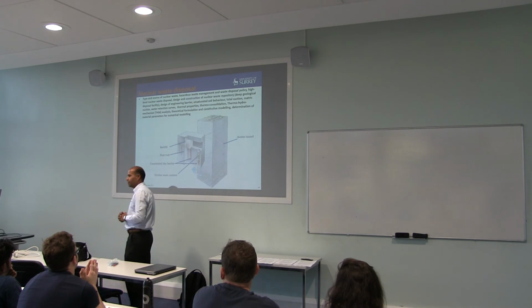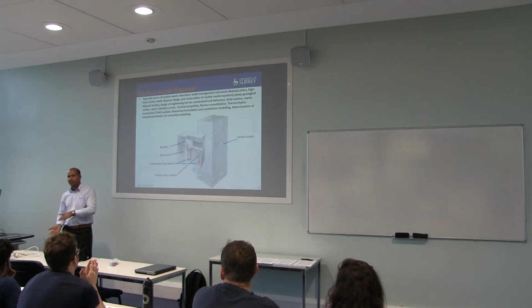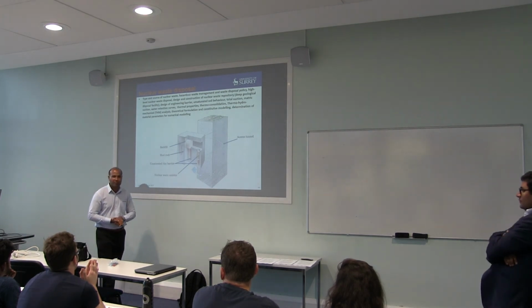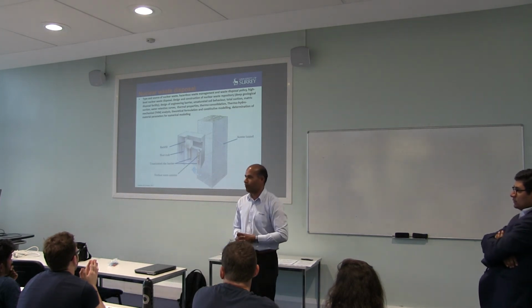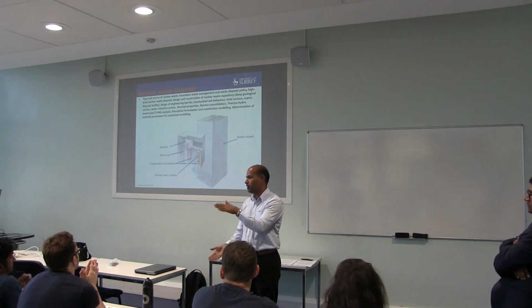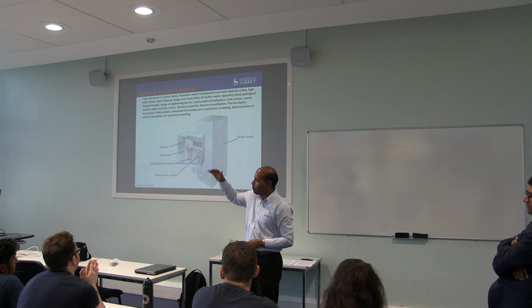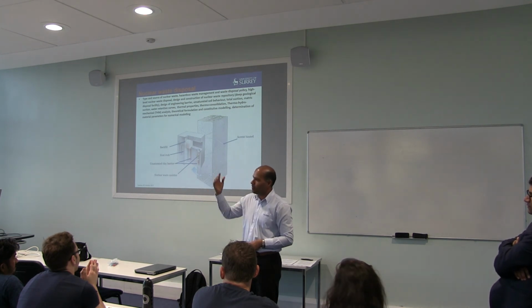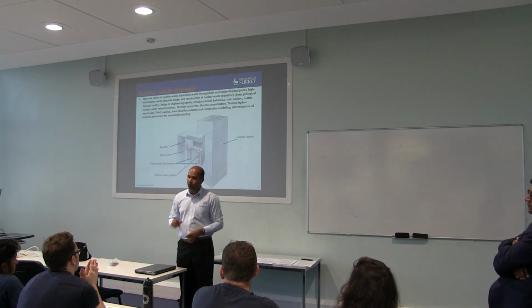Because if you have swelling clay at that site and rain comes, that clay will expand. If you have put a lot of money in your house, what will happen? It will crumble. You will have cracks. As I said, clay can swell by almost 200%, 300%. So if your room was on the ground floor, that can go up by half a meter or 1 meter. So you don't want to construct anything on swelling clay.